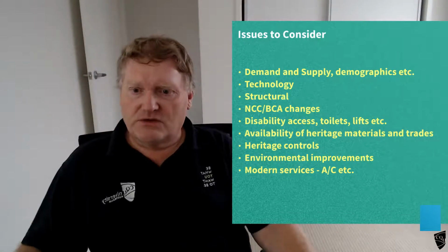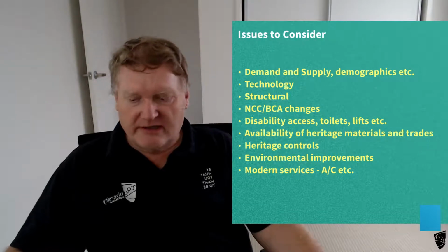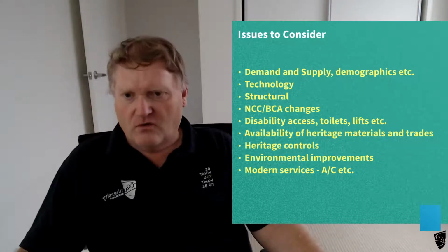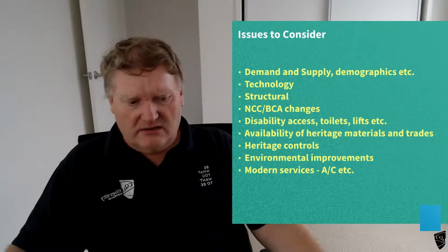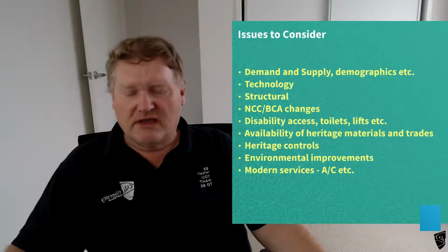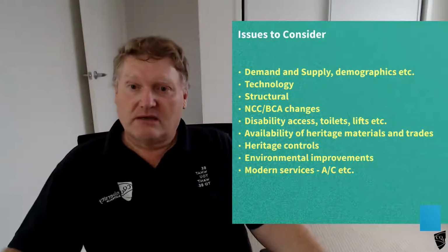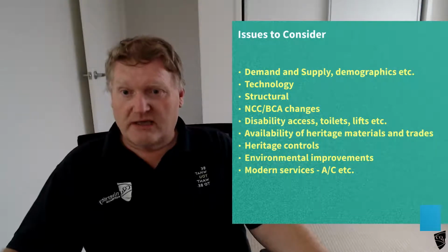Structurally, you need to consider, as I say, structurally. Some uses nowadays require stronger floor loadings, especially if you've got filing cabinets and compactors and large computer equipment and all that sort of stuff. So you need to be aware of the structural changes that may need to be made, especially if you're doing a change of use.